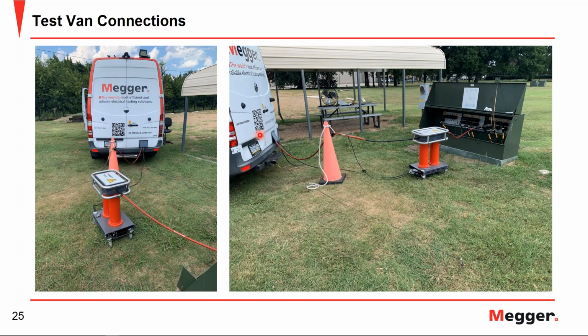So you've got a nice clean closed van. You can see that we have our ground coming out and connected. You may ask yourself, why is this high voltage cable tied to this traffic cone here? The reason is we really don't want the ground to influence our high voltage measurement. So it's ideal to keep that high voltage cable elevated and air insulated, so you don't have any influence of ground. And you notice that our ground connection also is not near our high voltage connection, so we're keeping some good distance there as well.